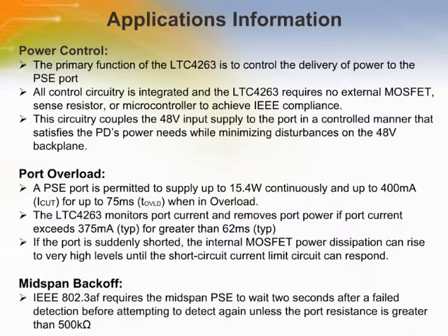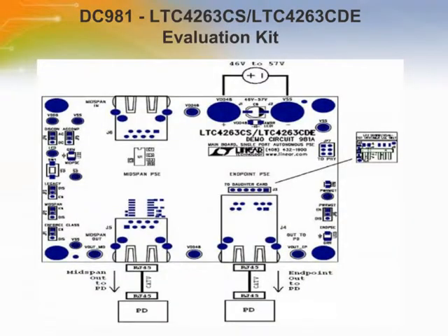This page gives you a brief introduction to application information like power control, port overload, mid-span backup, thermal protection, etc. Demonstration circuits 981A and 981B feature the LTC4263 in single-port Power over Ethernet power sourcing equipment, mid-span and endpoint solutions.